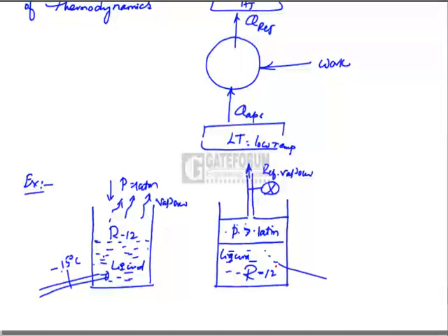Then if you keep the thermometer into the R12 liquid, we watch that the temperature now would not be minus 15 degrees centigrade as in the previous case. It may be, say, 1 degree centigrade. Now what we are seeing from these two figures, as the pressure over the surface of the refrigerant liquid is increasing, the saturation temperature is also increasing, as is seen by the thermometer.